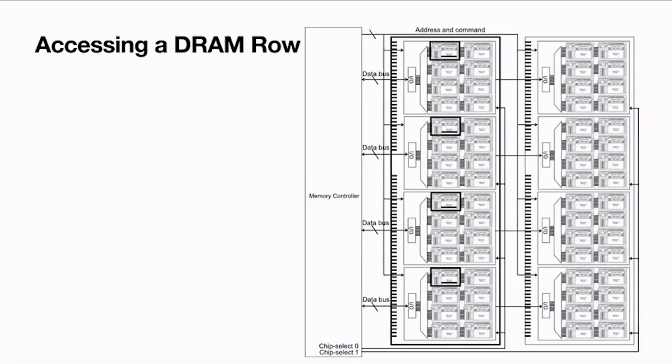When a request is sent, everyone is responding to that, and each will supply 1/4 of the data. So your total time for accessing the data is now reduced to 1/4. And that is the main advantage of placing the data in this order rather than placing everything into a single DRAM device.